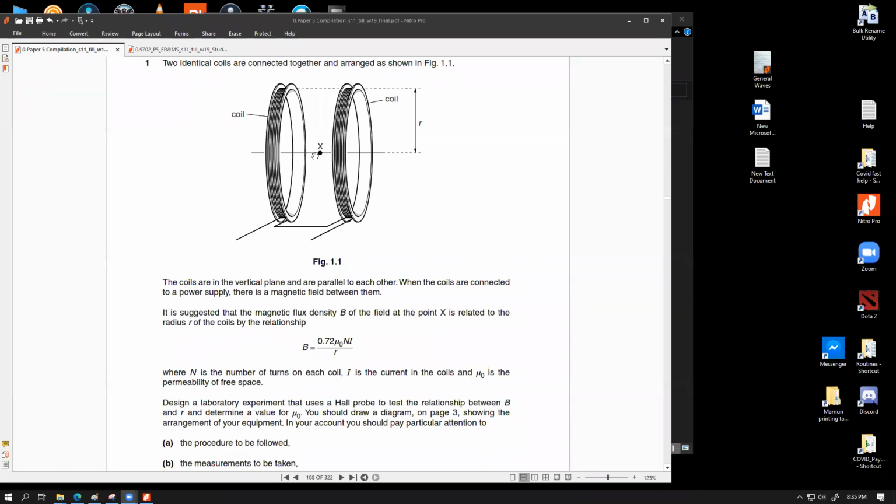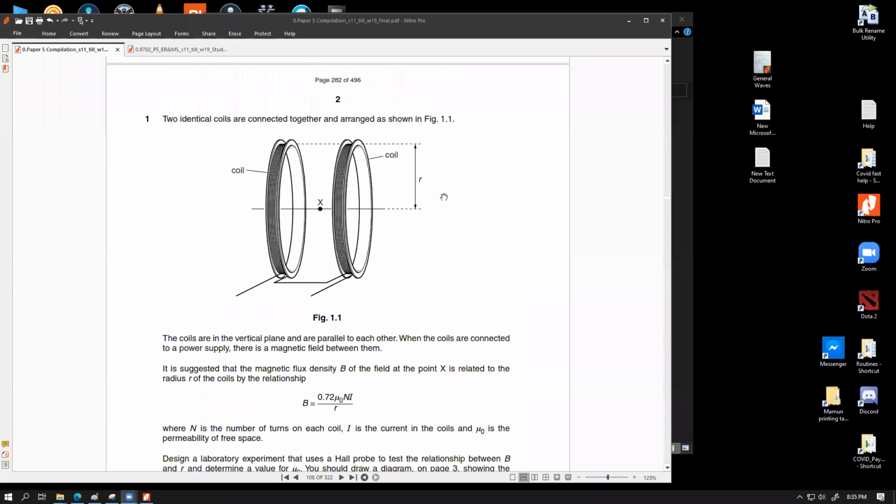To make sure that the Hall probe reading is perfectly accurate, we should place the Hall probe over here and rotate it around 3 different axes to get the maximum reading. This is pretty important because, if you think about it, if I take this picture out, hold up.